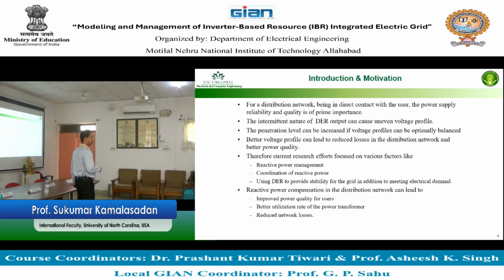You could solve the problem just using controllers, which I found very interesting. That is actually just managing the device with respect to the device capacity. You could also solve the problem by introducing new devices, for example FACTS devices, or capacitors, or a combination, or some new inverters. You can also include energy delivering devices like reactors, though that is passive. Active energy delivering devices like batteries and other devices can also be connected.